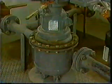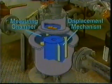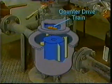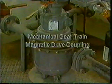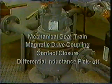Inside the housing is the precision measuring unit, made up of the measuring chamber and the displacement mechanism. The counter drive train transmits the internal motion of the measuring unit into a usable output signal. This train may be a mechanical gear train, a magnetic drive coupling, a contact closure, differential inductance pickoff, or a combination of the above.